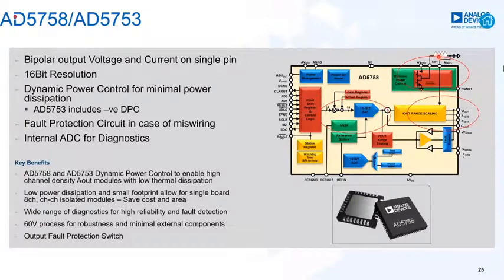What is the disadvantage of that? You won't be able to increase your output channel density, because increased power means increased thermals, and increased thermals mean more and more drift parameters associated with your design. So you will have to limit your number of output channels if you do not have good power schemes in place.